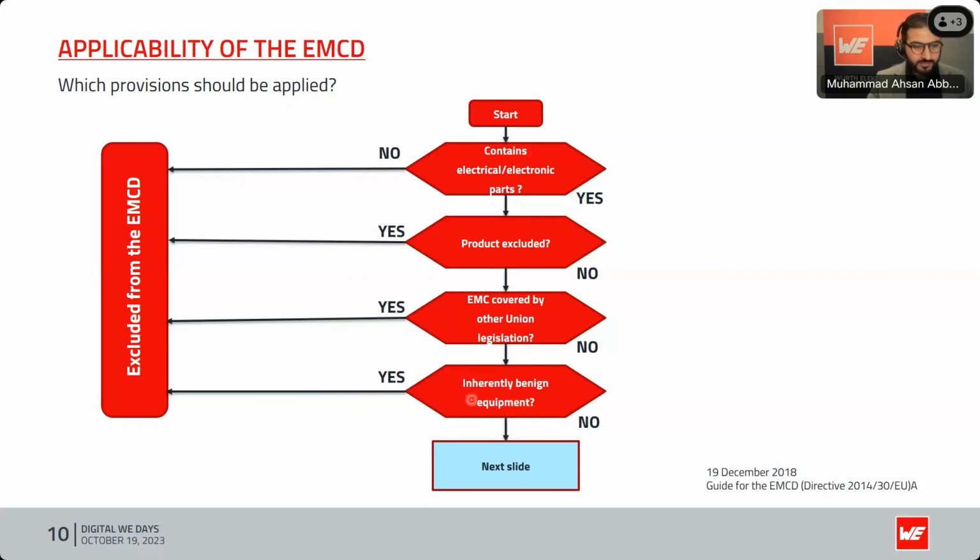But this is sometimes not easy, because I saw an interesting presentation from the Bundesnetzagentur, where they showed the results of different products which were using ready-made connecting devices like coaxial or HDMI cables. The shielding was very poor due to low manufacturing cost. Apparently, such a ready-made connecting device looks like it has no impact on EMC because it doesn't directly have any electrical component, but no, because it is mostly used with multimedia equipment, and it really impacts the EMC performance of the complete application or system later on. So you need to be careful here.